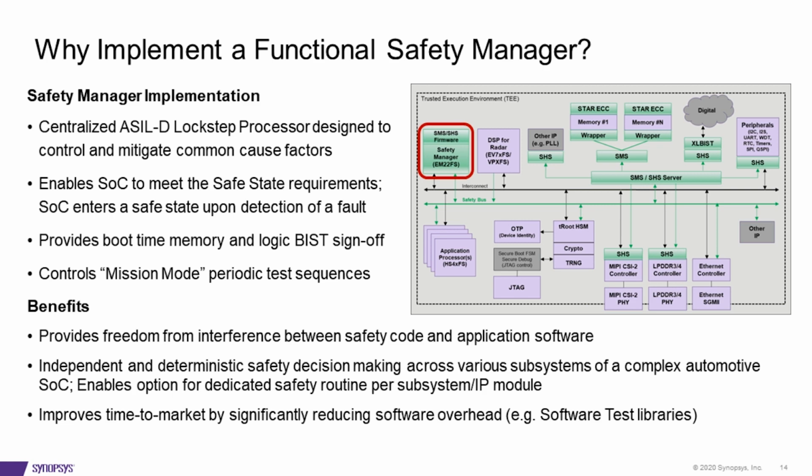But maybe there's another, less safety-critical area or subsystem within the SoC where the safety escalation does not require a full reset; maybe it can continue to run without having to reset the part. Those decisions can all be made by the software in the safety manager, and allow the integrator to make decisions on what needs to be done from a safety-related aspect that's independent of what needs to be done functionally.